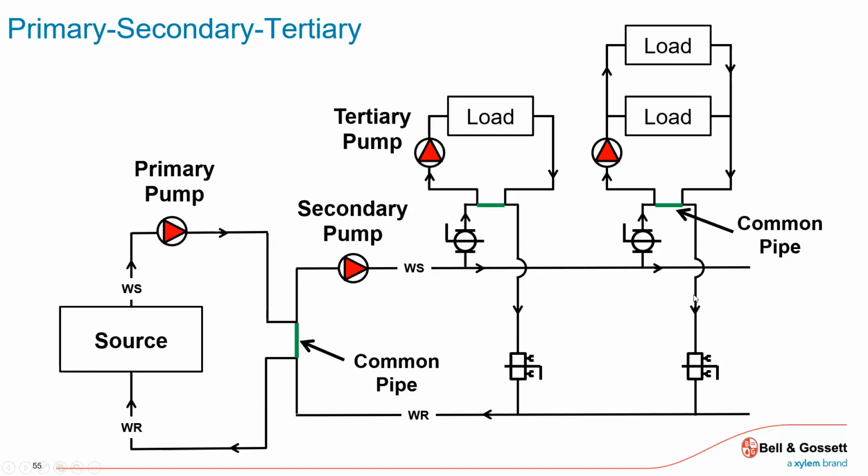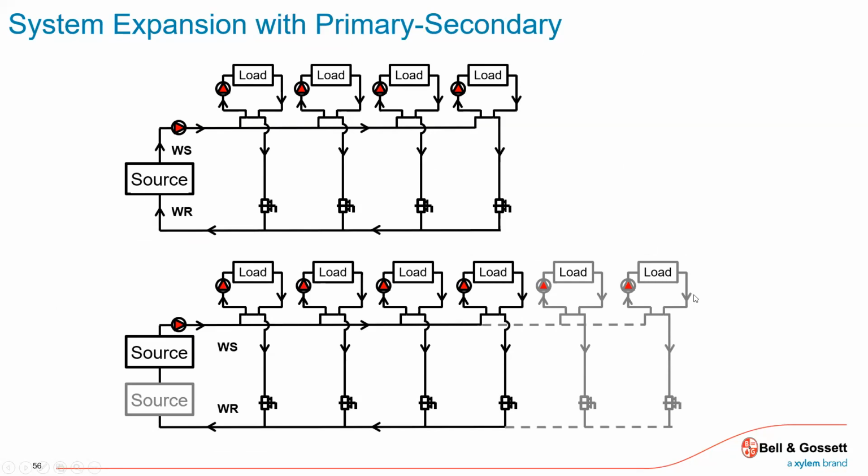So they simplify the drawings. It's your imagination and application. It's really getting the concept of decoupling and all the benefits versus trying to do all of this with one big pump with this really high head. And then I got all of these control valves that are trying to open and close against a really high differential and maybe an excessive horsepower requirement. So maybe I can start using these smaller pumps, and then when I add up all the horsepower, it's not excessive, it's actually less, and it's smoother control because I'm using smaller headed pressure differential pumps that are size specific to their necessary loads or needs.